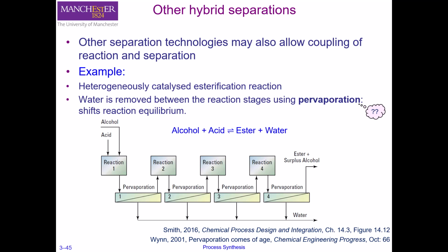The type of membrane separation method that we are using here is called pervaporation. Pervaporation is a membrane separation process in which the upstream of the membrane is in contact with a feed liquid, while a vacuum is applied on the downstream of the membrane, and the liquid permeate, the liquid that travels through the membrane, vaporizes somewhere between the upstream and the downstream side of the membrane.